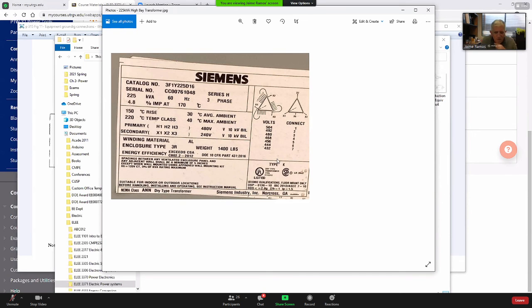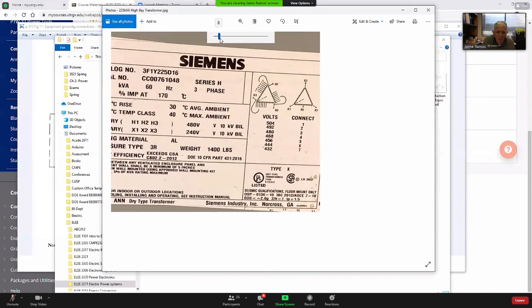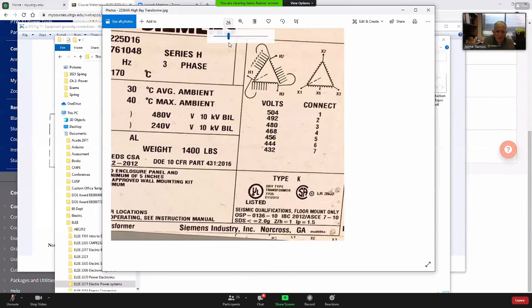Okay. So then look at this. It's really interesting. Let me see, where can I increase this more? Okay, so let's first look at the left. The primary has different tap connections. Okay. So we can move the connection and increase or decrease the number of turns. So look, it's 480 nominal.